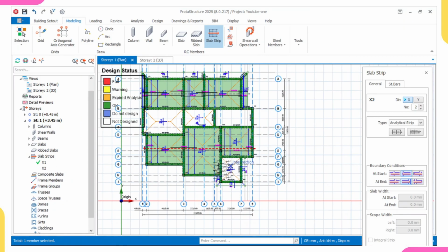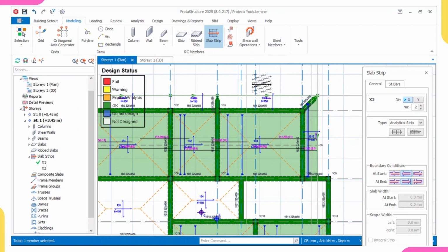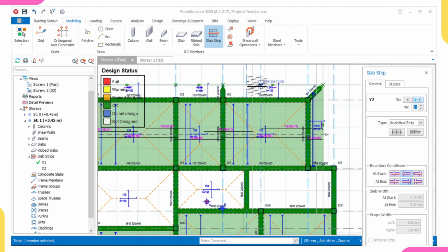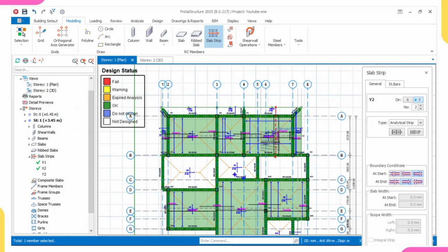So this is what we're having. In this case now, okay, look at it. Let's do this case now. This one is now Y direction. I said I will not do everything to save time. So this is now Y direction. If you look at this one, I'm having cantilever and slab. So I'll click on this. Here, I'm having slab and beam. So look at it, slab and beam ending. So I'll click on this. I'll go from here, hold my control key, to here. It has designed this in Y direction.